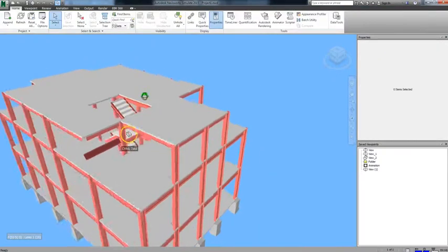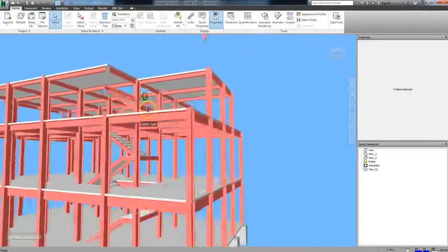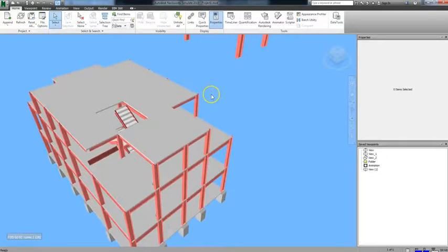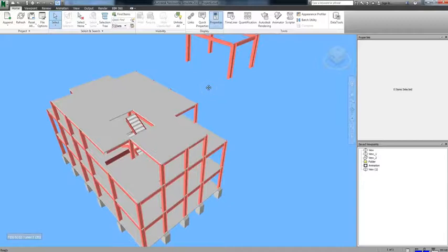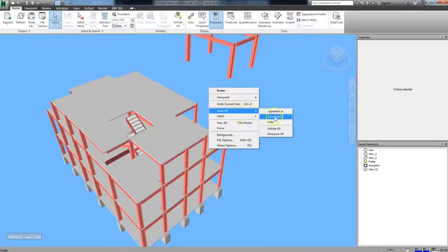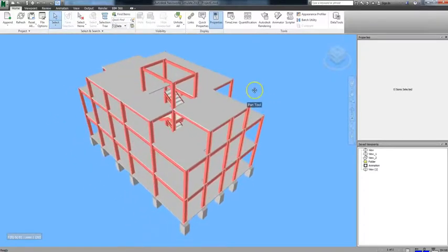And just as when you overrode the color and the transparency, you can easily reset any transforms that you make. Simply right-click anywhere in the scene that's not on an item, go to Reset All, and choose Transforms.